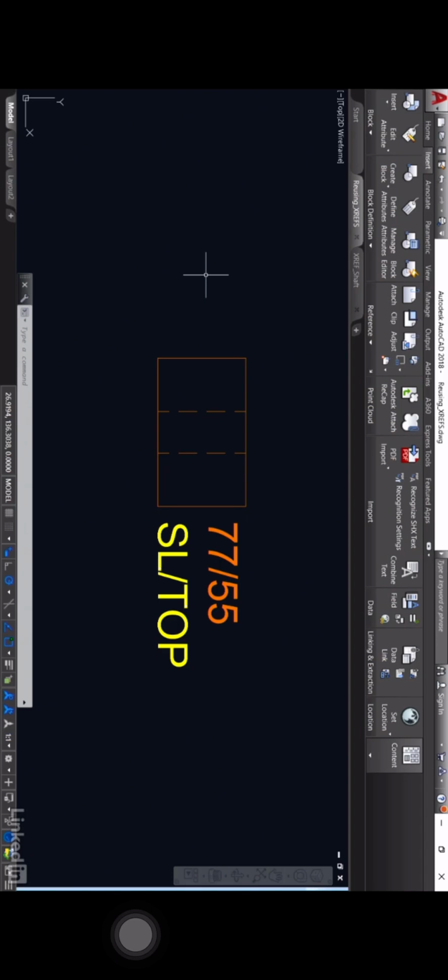Well, we go to the Insert tab on the ribbon, we go to the Reference panel, and we click on Attach there. And you can see that goes to the folder where all my drawings are for this particular chapter. There's the XREF shaft drawing there. You can ignore all these DWL files. Basically, they're telling me that those files are already open and are locked. So if I tried to open those at the moment, it would prompt me only to open a read-only version of the file. There's XREF shaft there. A little preview of it there as well.